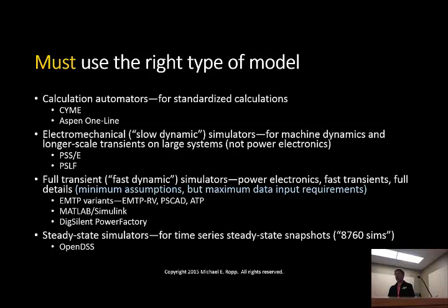It's that other 15%, you got to know where that 15% is. For big system simulations, like if you're trying to simulate the entire Eastern Interconnect or something like that, you would use a simulator like PSSE or PSLF. These are sometimes referred to as electromechanical simulators. They are phasor domain simulators. They are time domain, but using a phasor representation of the system.